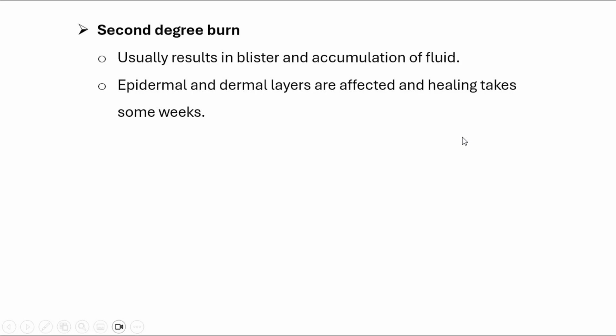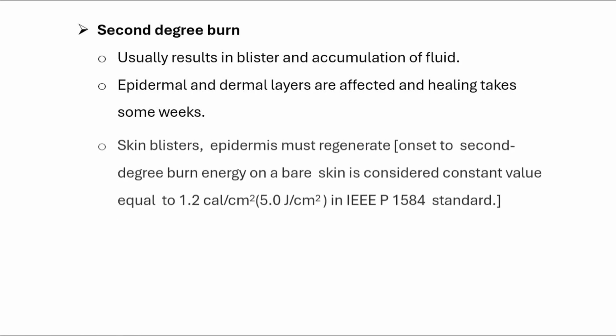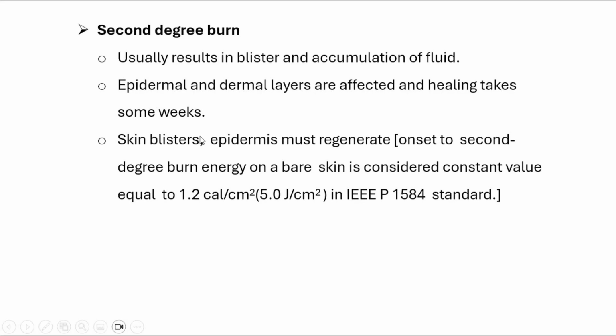The epidermis of the skin blister must regenerate. The energy on the bare skin at the onset of the degree of burn is considered constant, with a value equal to 1.2 calories per centimeter square. This is per the IEEE standard.